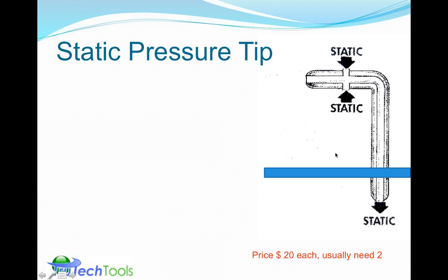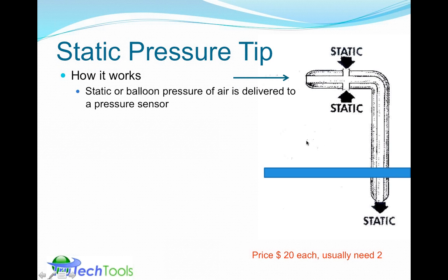Sometimes you can hear ducts inflating in larger systems going boom, boom, boom, boom, boom as the system turns on. If you hear a large air handler turn on, that kind of pressure that's inflating the duct is the static pressure. So this total pressure moving into it is not actually sensed by the static pressure tip.